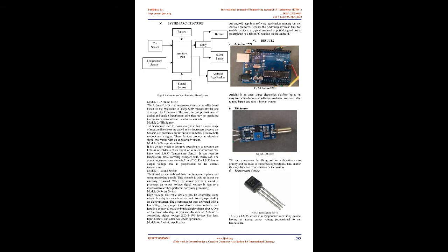and eliminating manual power to the highest possible extent. 3. Proposed system. The main idea is to design a portable wireless sensor node which will be a part of a wireless sensor network. This system will consist of 2 modules, one involving the sensors and controller module which will be at the tree spot, and the other one is an Android phone. This is an IoT-based project. In the case of the tilt sensor, the buzzer turns on when the tree bends, and for the temperature sensor, the water pump is turned on in case of forest fire through the relay switch.